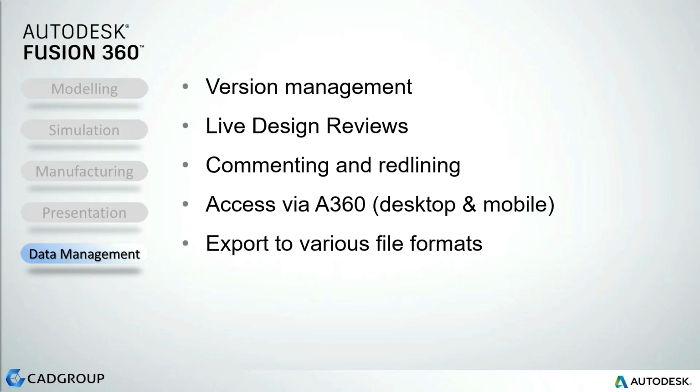And which is something that I find really cool as well, is the ability to export it to various file formats. This typically means that, if you've sent files out to other people, you might be asked to send them out in a specific file format. So you export it, save it into SAT format, you send it to the guy, and then the guy says, oh, I can't open that, then you save it in another format. With Fusion 360, they can actually access it in A360, and they can download that specific format for themselves. I'll show you that in a while as well.